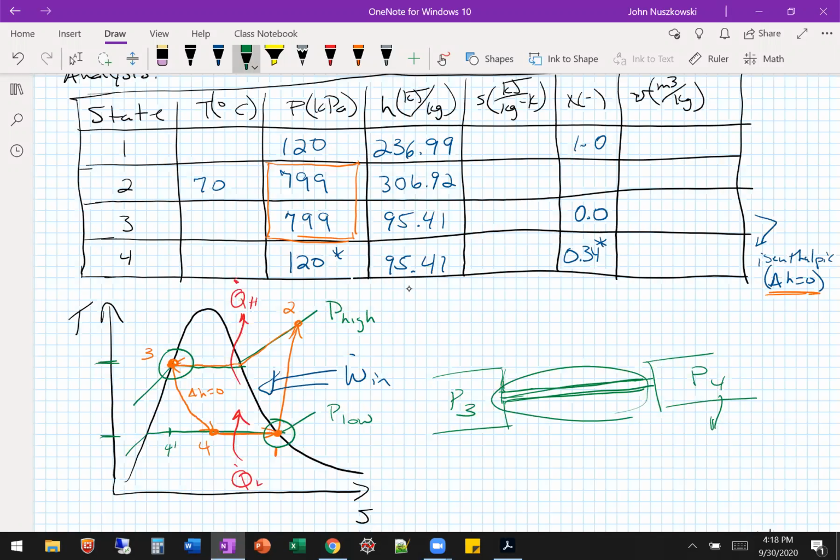If it didn't, and we'll talk about this in chapter 12, hydrogen, I think it's hydrogen, or is it helium, one of those, depending upon what temperature you're at, will increase in temperature when you drop pressure versus decrease. So then it doesn't work well as a refrigerant at those ranges. So when you drop pressure, you want it to be a fluid that drops temperature also.